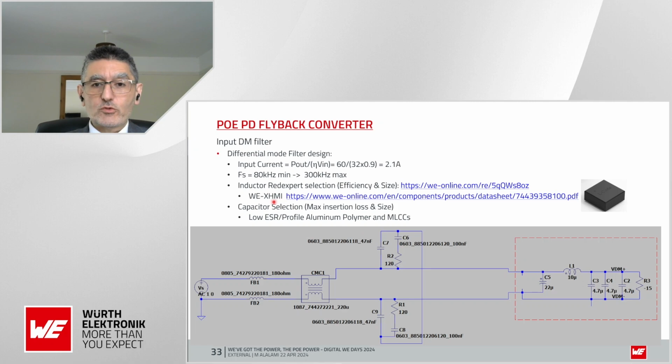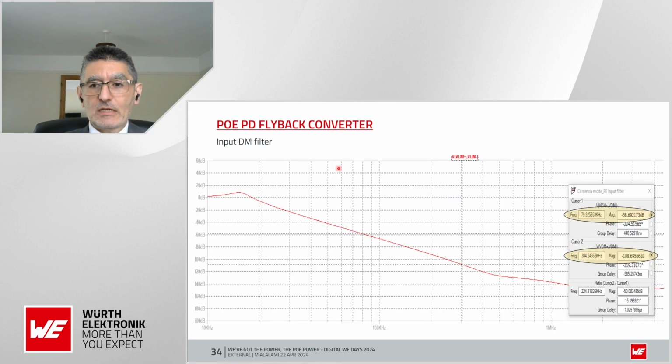The same concept was also followed for selecting the capacitors here: size, as well as, of course, maximizing insertion loss, having the highest capacitance that we can have, basically. With this, we again tested at the two frequencies of interest, and again, we get a substantial amount of insertion loss at both frequencies for that filter.